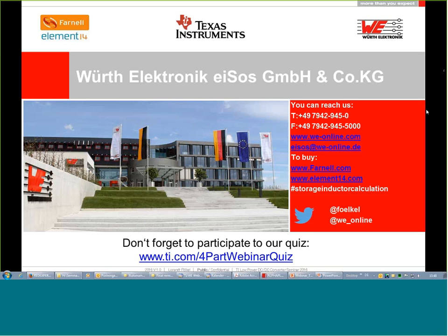And what I had in my experience, I just take the inductance and turn the PCB 180 degrees on the soldering point. Normally, if you look at the surface mount inductors, they always have a dot on the top. This dot means the beginning of the winding. And if you put this dot in the direction of the switch node, to the IC, normally they don't start singing.